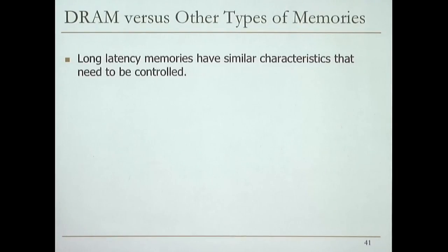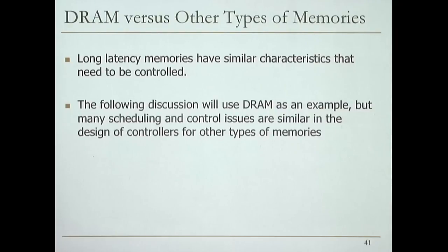Remember, I asked you the question, does flash require refresh? Even though it's non-volatile, it does require refresh also. So you need to control these characteristics. So the following discussion that we will have in this lecture about memory controller, we'll use DRAM as an example. But many scheduling and control issues are actually similar in different controllers. So if you actually know how to design one controller really well, you could potentially design some other controller really well also. Of course, you need to adapt to the different characteristics of different memories.